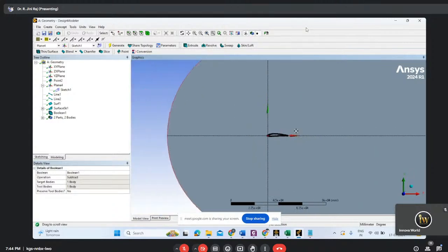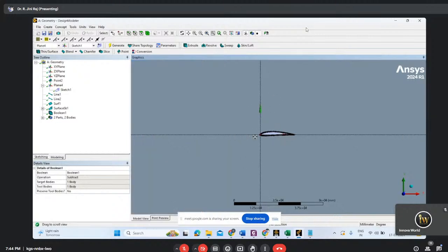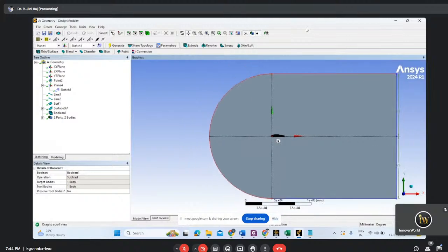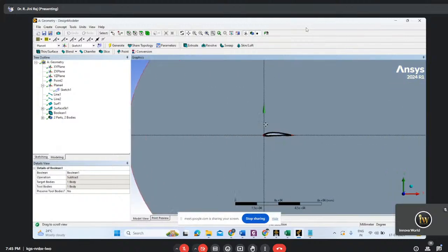Now, if I want to go for structured type mesh, then we should split the faces. Or else, one method is there where we can go for structured plus unstructured, but it will take time for meshing itself. But other things, analysis parts and solution parts, will take the same time only. So for now, I will teach you how to do the structured grid.